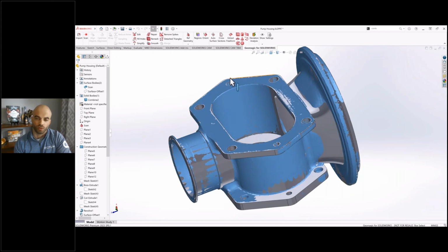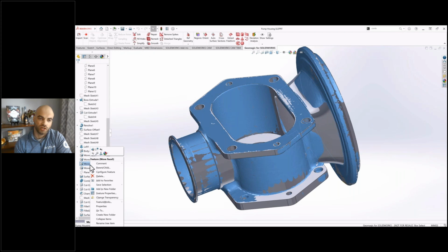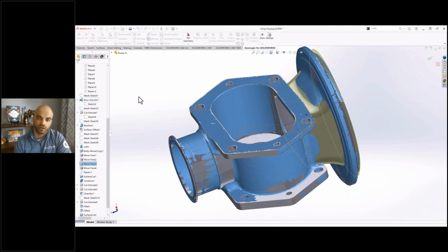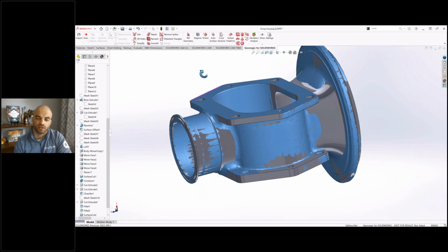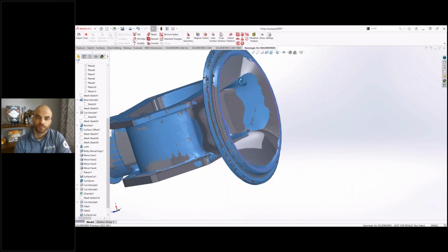Because remember, we are going away from the original design. I mean, this kind of looks like it was maybe hand built, and going with that offset instead of doing a second loft, I expected there to be some deviation. What I just didn't want to do is take away material in areas where it could be critical. So I'm going to bump that offset up a millimeter just to see how close we're getting then. And that should give us a little bit more wall thickness to make sure that at least we're getting rid of the blue spots on that surface.